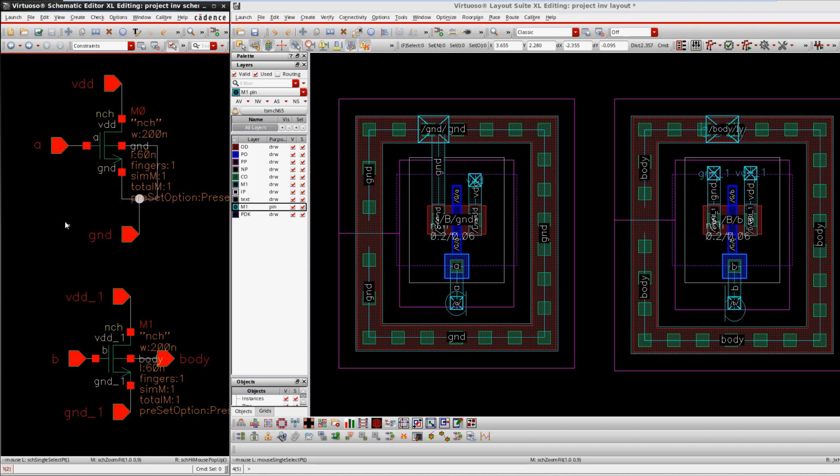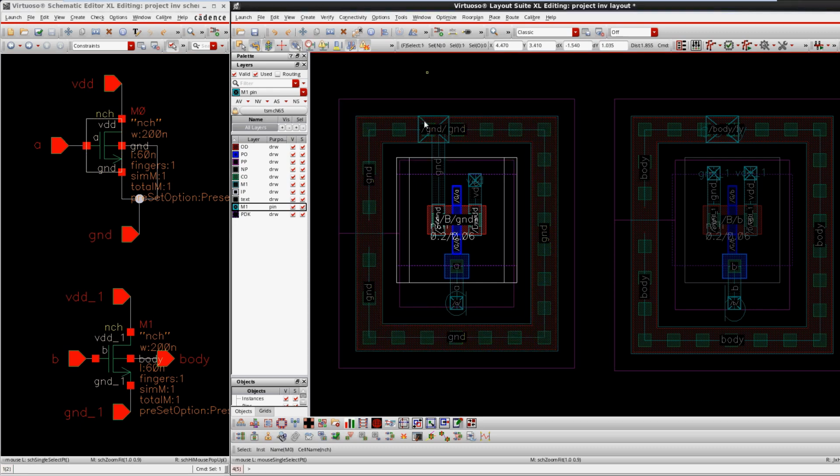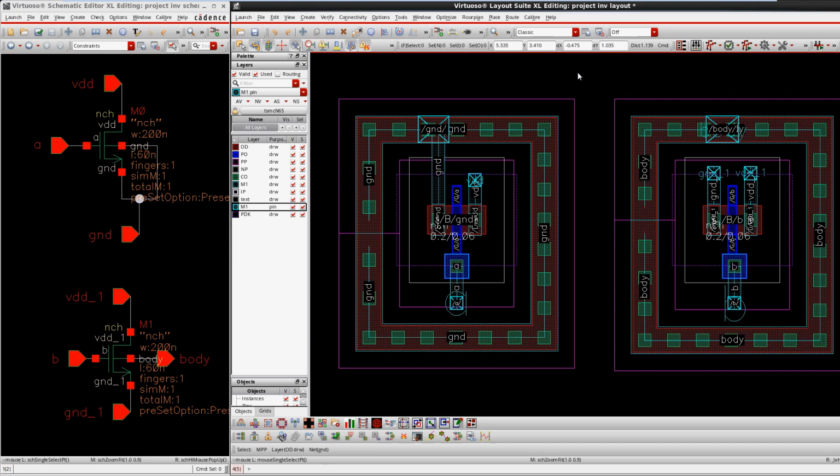We have elaborated completely why the tool is showing this error, since based on the schematic diagram some people cannot understand why it is showing. That is why I have given three different classifications: one based on the schematic view, one based on the layout view, and one based on the cross-sectional view. We have completely discussed these three types of problems. One is based on the cross-sectional view, where I explained why we need DNW insertion and why the tool is showing the problem.